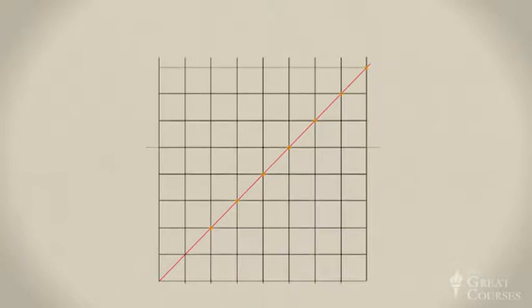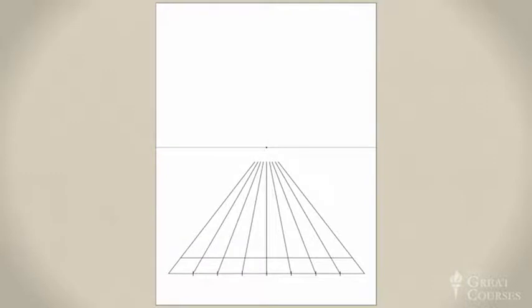Think about it for a moment. Might want to pause here. Many of you likely got it. The solution involves drawing a diagonal through the opposite corners of one of the bottom squares, and then projecting that diagonal across the vertical lines. We note where the diagonal crosses the verticals, and draw a horizontal at each traverse to create the grid. And this will work precisely the same way in the foreshortened position.